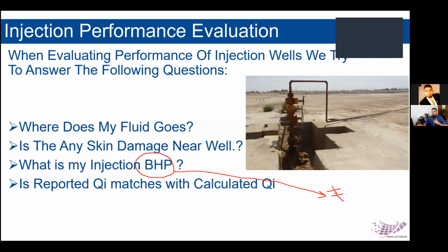And whenever you have the bottom hole pressure decreasing, it means that you have channeling, or your well is performing much better than you think. These all actually require operational data to monitor and measure.